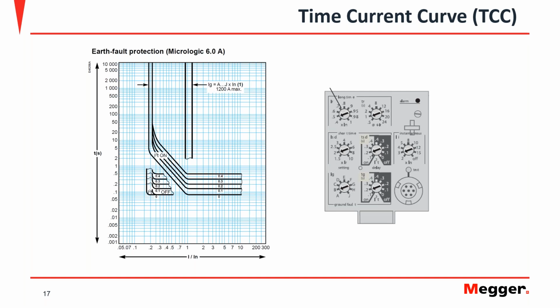However, it is important to mention that if you do have some type of secondary scheme where this may communicate to another device within your protective system, you need to understand what that is before you perform this test. If the device that you're trying to test trips, it may communicate to another device and then trip something else in your system. While this test is done with your system offline, it is important to make sure that you're not going to trip something in the system that you don't want to take down.